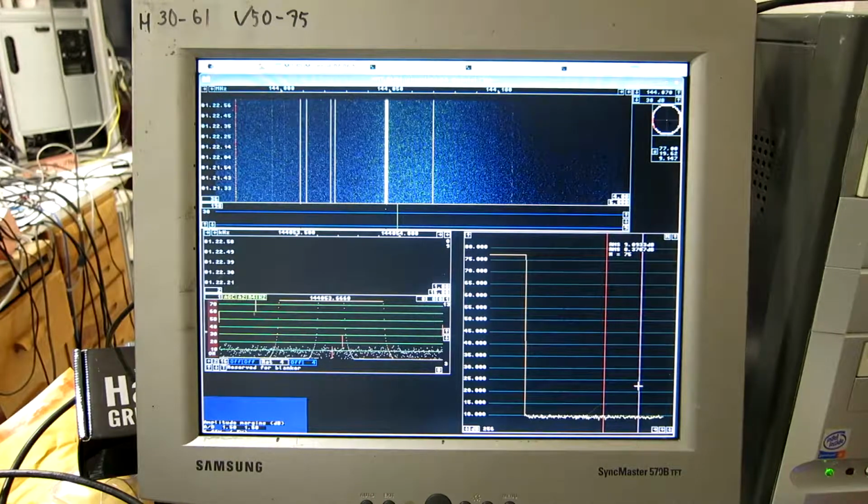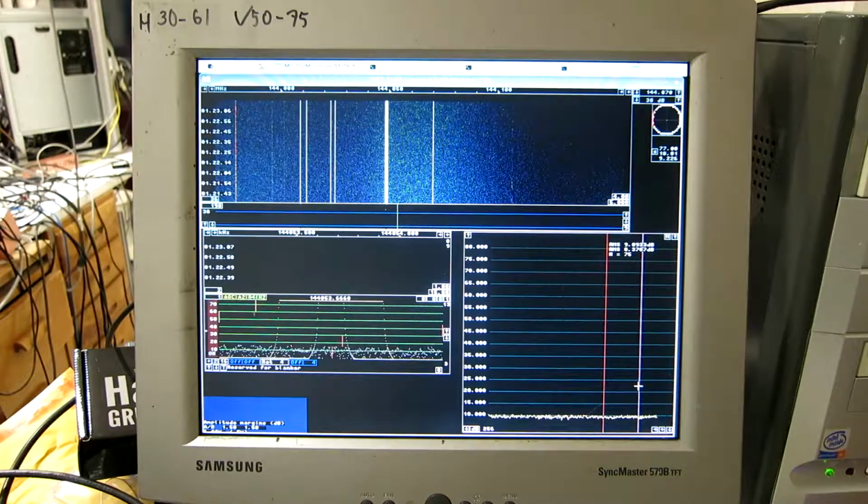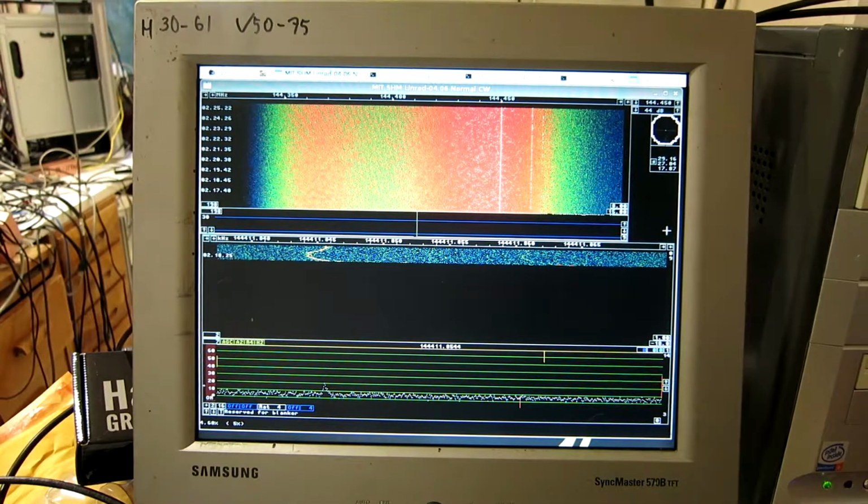If you don't need those 6 decibels of extra dynamic range, then of course run the dongle at 300 kHz or maybe even at 230 to make processing far less critical on slow computers. This is economy settings for a slow computer. The load, as you can see down in the left corner here, is less than 5%.